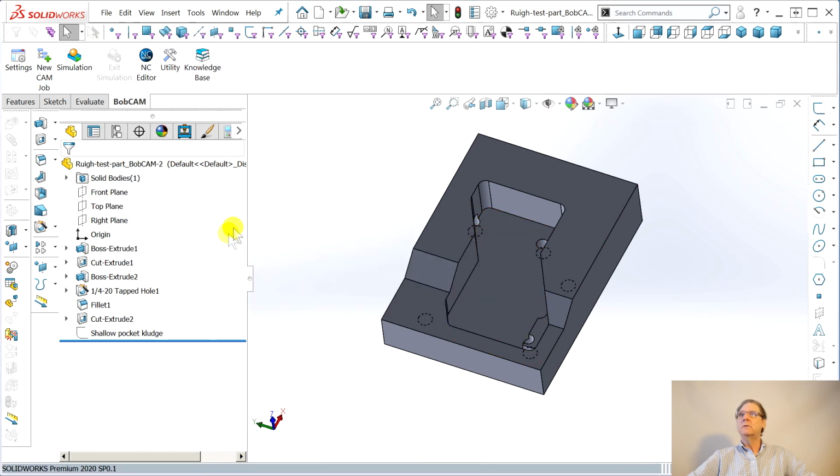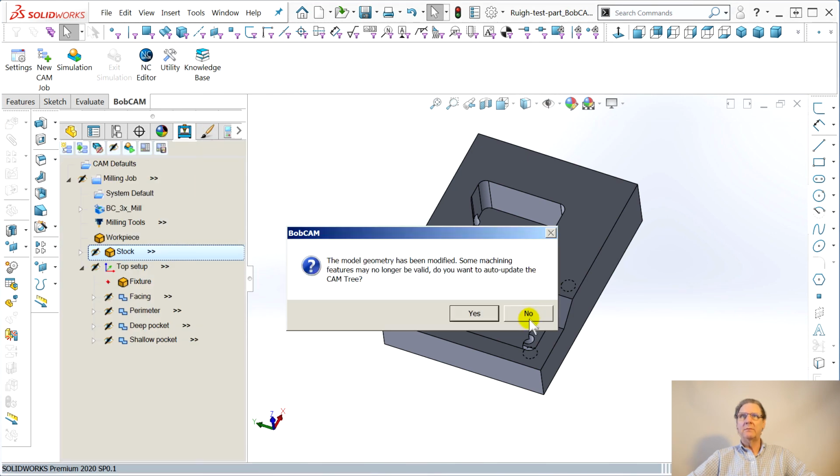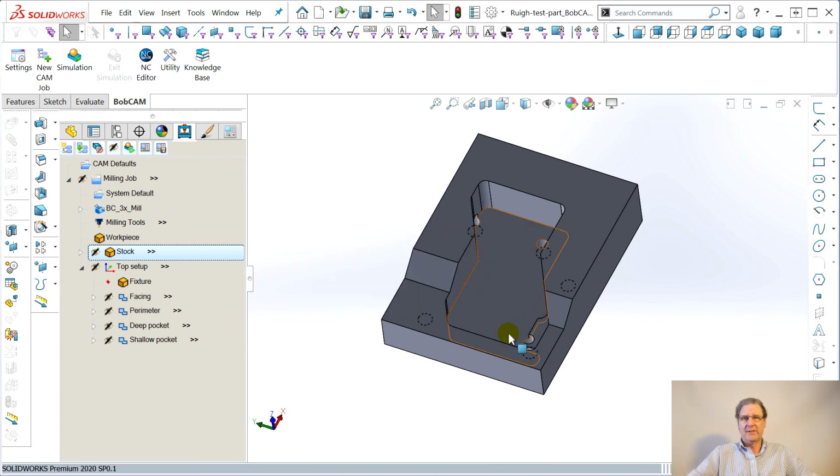See, it wants to change stuff. SolidWorks CAM does automatic feature recognition. All the holes that you change from giant 3/4 inch holes to a milled hole show up again and drills come back. So I've been saying, no, this won't affect any toolpath. All you did is draw a sketch. But this is how everybody works: you change the model, it automatically changes. We'll play with that next round of CAM evaluations.